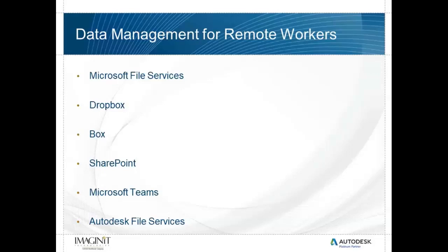But then, as some of you on this call know, Autodesk has some problems with these types of setups: file locking doesn't happen, somebody overwrites somebody else's file, reference files are missing, data shortcuts are missing from Civil 3D, and Revit model corruption occurs because 2 people are trying to modify the same element at once. There are a lot of inherent problems in some of these common file services that people use for Word documents and PDF documents that don't necessarily work all that well in the Revit and Civil 3D world.